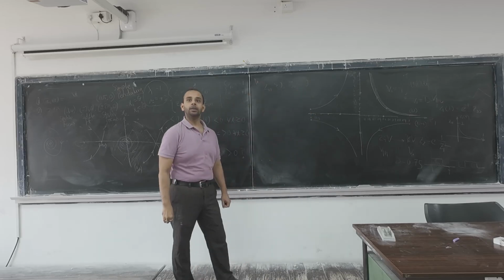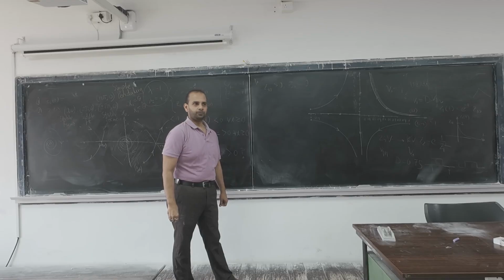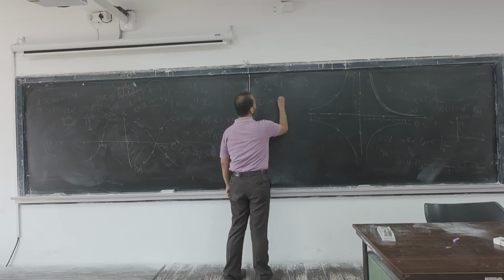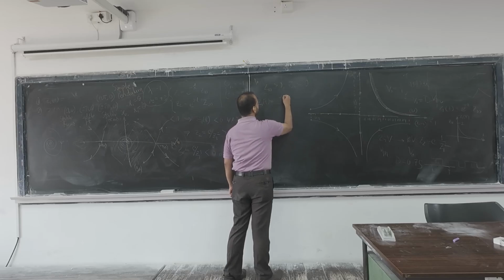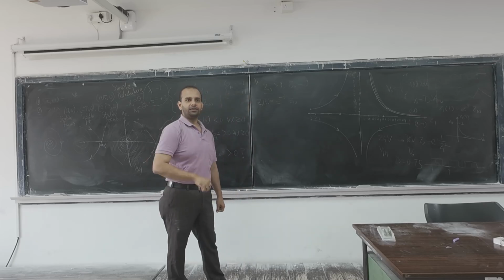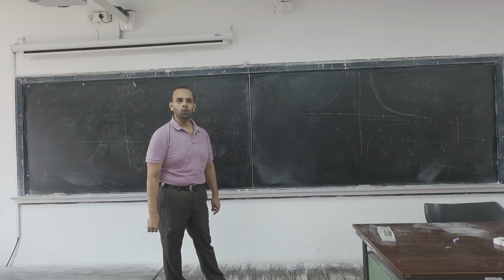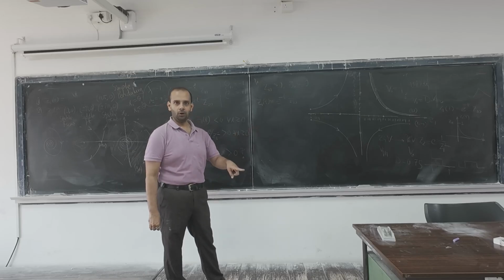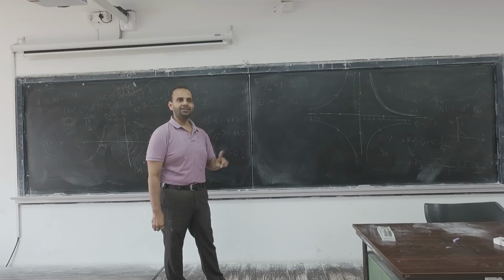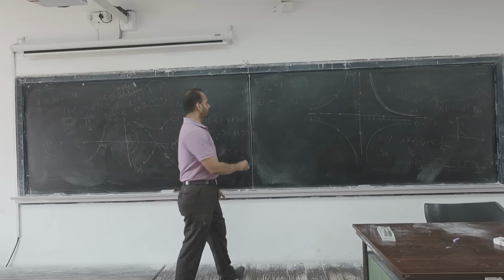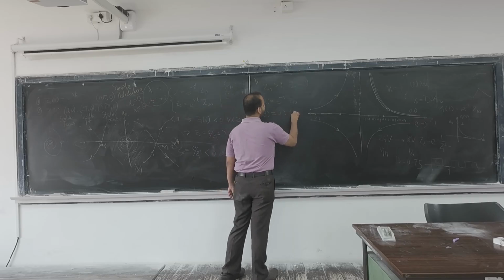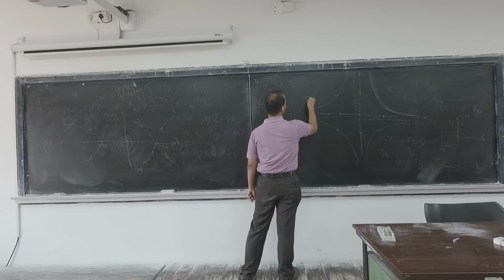That is my case. Then what will happen? Z1(t) will be e to the power minus t times Z1(0). That will be a decreasing value. But what about Z2? Z2 is e to the power 2t times Z2(0). Although it is an unstable mode, at least in the coupled system, if the initial condition is 0, then Z2(t) equals 0 for all t greater than or equal to 0, right?